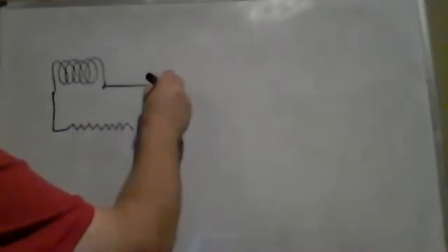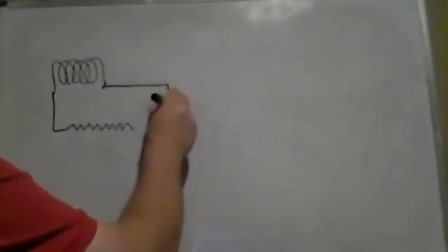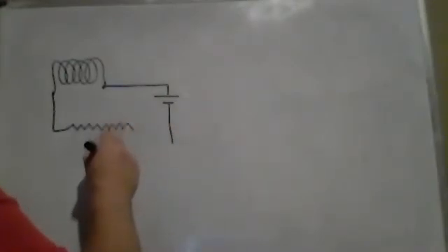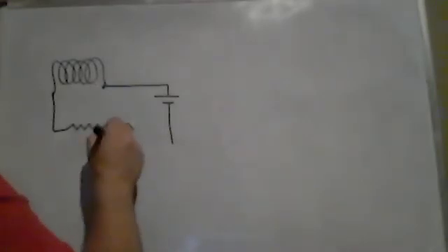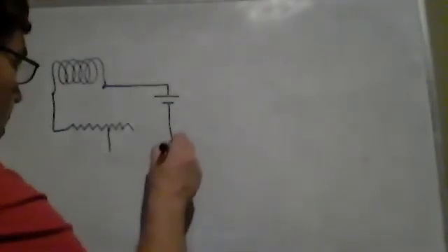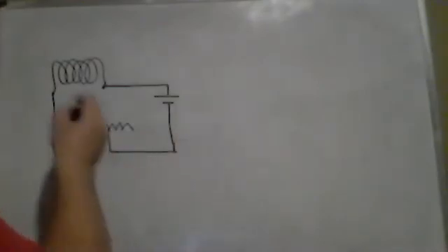Okay, so I have a coil. Come around, I'm going to have a battery on the end. And I'm going to connect the coil someplace on the resistor. Remember, the resistor has resistivity, and R is rho L over A. I can control the resistance by how much length I allow the resistor to have. So again, you have a variable resistor like a rheostat, where you actually touch along the resistor, you're determining the resistance. All right, so this is a variable resistor.